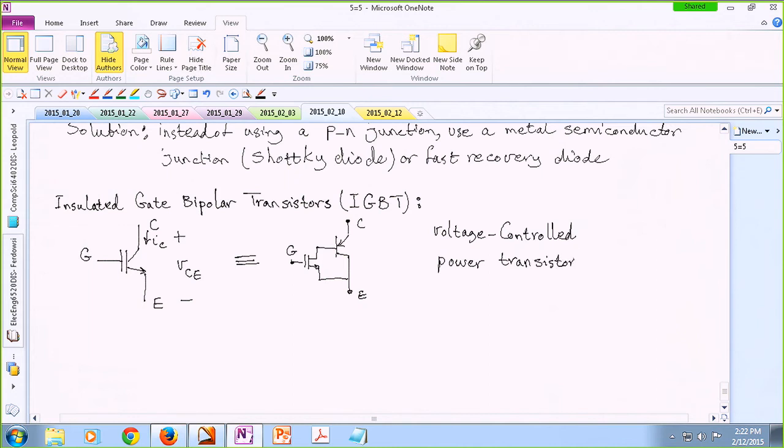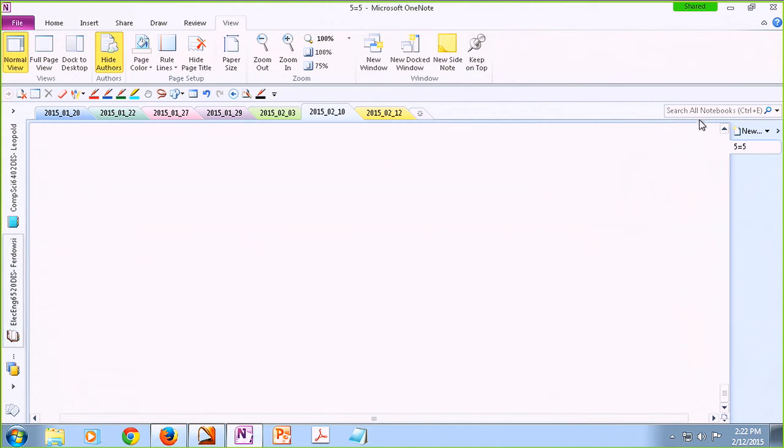Okay. So if you look at the data sheet, if the voltage applied from gate to emitter is beyond a number, like more than, for instance, 10 volts, then your device is guaranteed to be on. If it is 0 or sometimes a negative value, like -5 or 0, then your device is turned off. All right, so what about the volt-ampere characteristic? If you look at the data sheet of an IGBT, you will see something like this.